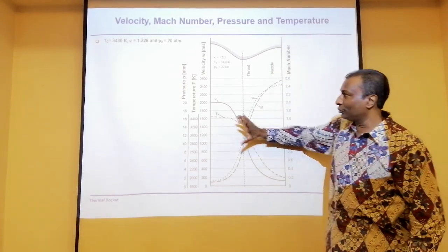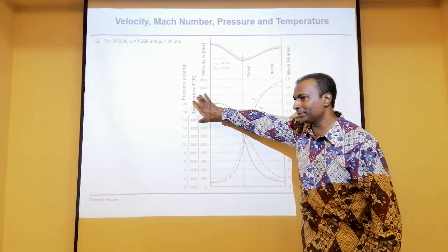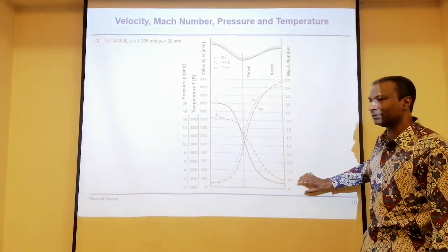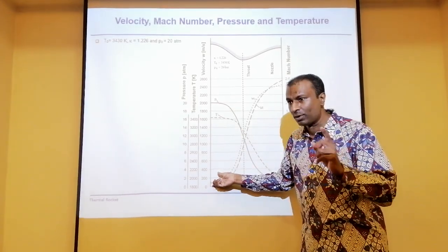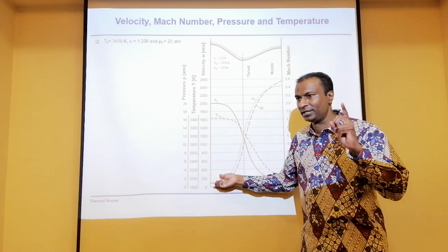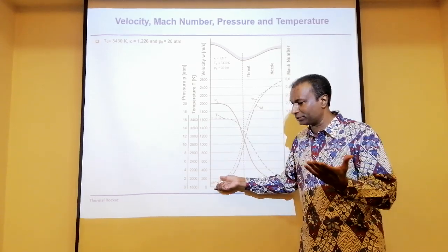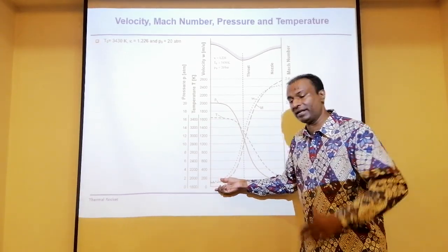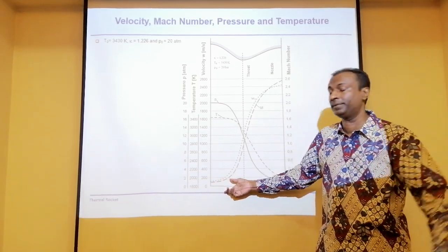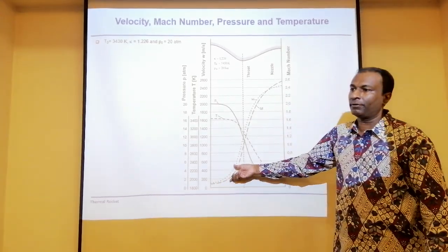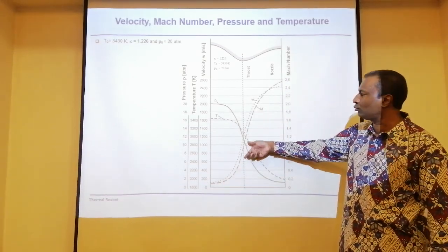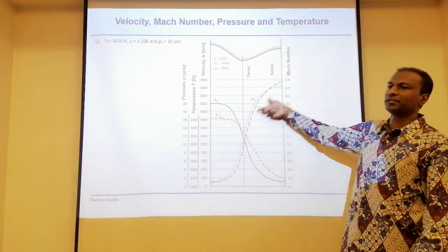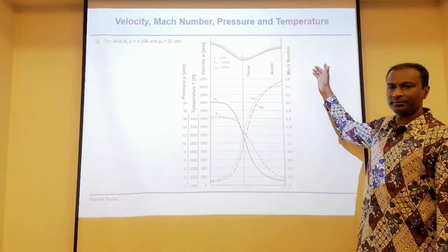Okay, so two major parameters drops from maximum to minimum. Two major parameters that what we wanted, which is the exit velocity. The Mach number is important, and of course the exit velocity. When exit velocity high, obviously Mach number will be high. From minimum or zero before ignition, goes through the throat and spikes out. This is exactly what we want.